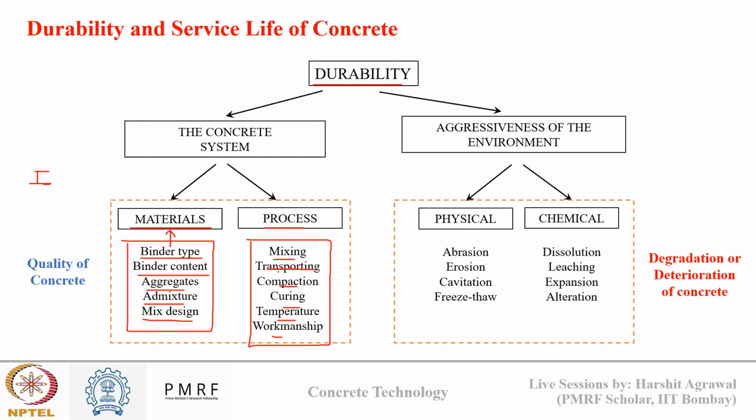But suppose there is a delay in transportation or there is improper compaction, then there will be big voids in concrete, which will raise durability issues. Or if curing is not done properly, even though we have chosen all the material compositions properly, the concrete won't gain enough strength. In this way, process can also define the durability of a concrete.